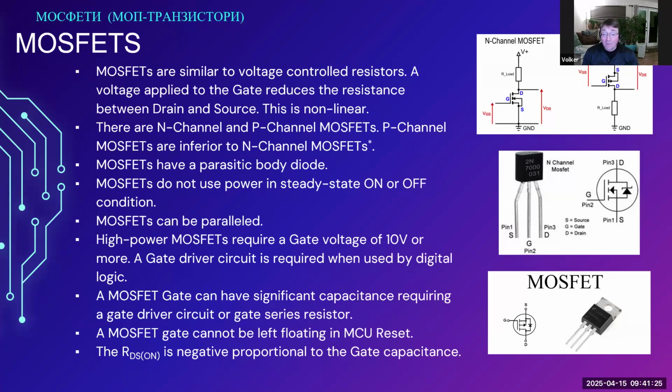Even if you don't use a specific gate driver circuit, if you don't switch very often, sometimes it is sufficient to just use a resistor, like a pull down resistor in this case, between gate and source, to discharge the gate if necessary. This, of course, would have the effect that it is very fast to turn on the MOSFET, and it takes a long time to turn off the MOSFET. Again, possibly requiring compensation in firmware for dead times when setting up the PWM peripheral on a microcontroller.